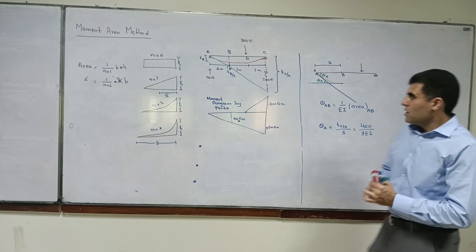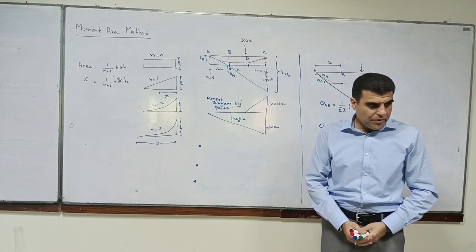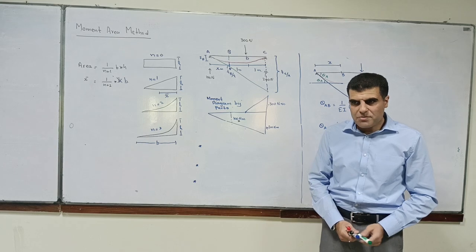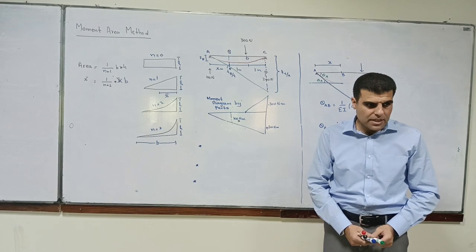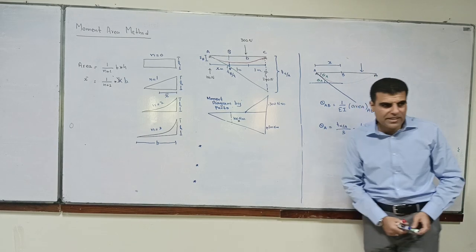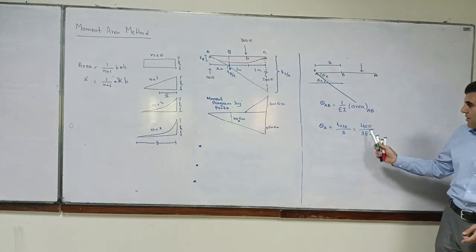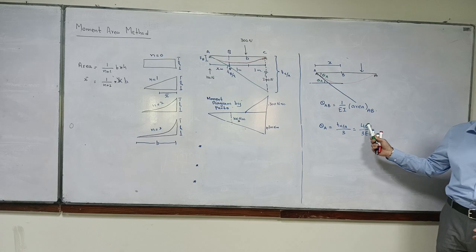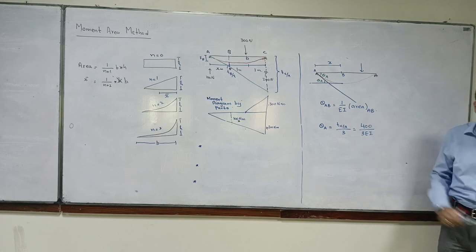Look, we are doing small displacement. Okay? So tan theta is approximately equal to theta. So therefore we omit tan. And so 400, this TC by A was 400. Yeah? So this is 400 by 3 EI.